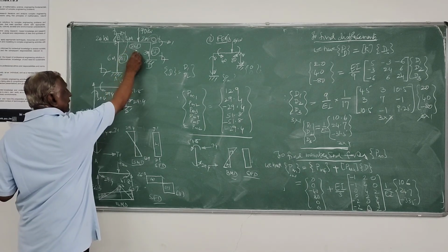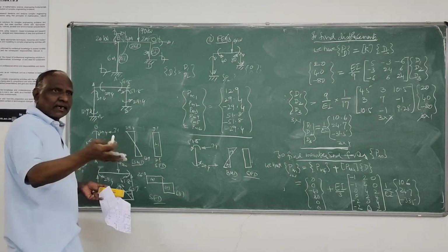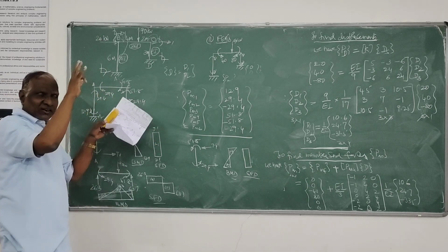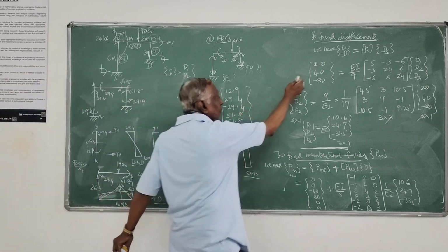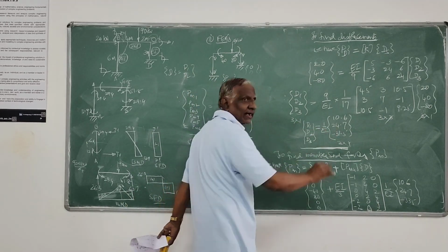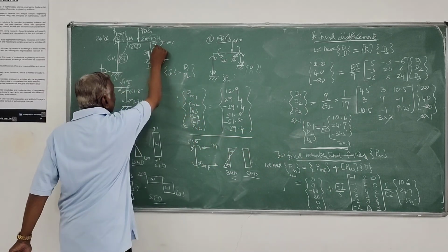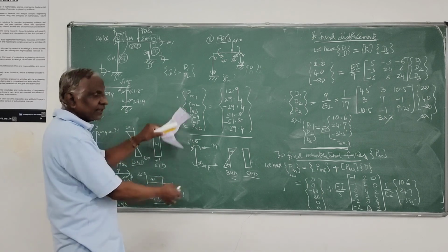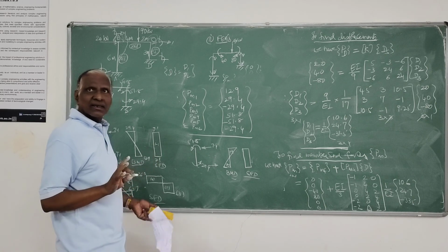Because this is unsymmetric, don't be under the impression this will not move at all. It has to move. I told this, I think, in Kani's method also. Don't be under the impression that only if a horizontal load is there, the frame sways. The only change is in the computation of PD. PD will become 0. It doesn't matter. D1 you will definitely get, whatever value, even if no horizontal load is there. Because it is sway, horizontal movement will be there. It will not be 0. But that gets redistributed among the other members during that process. You have to be very, very careful.